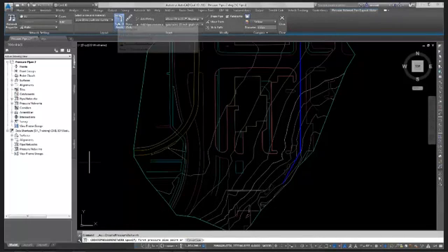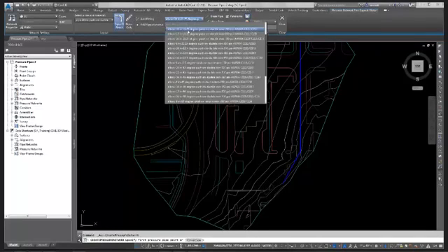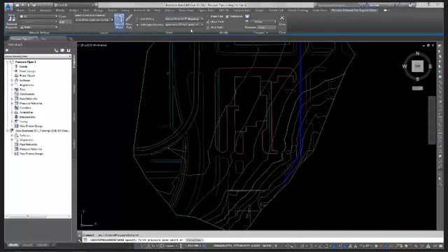So I have by default 10-inch, but there are the 4 styles I have. My elbows, 10, 12, 16, 6 at 11 1/4. Then I've got 22 1/2, 45, and 90. The appurtenances, I have the gate valves, 6, 10, 12, 16.